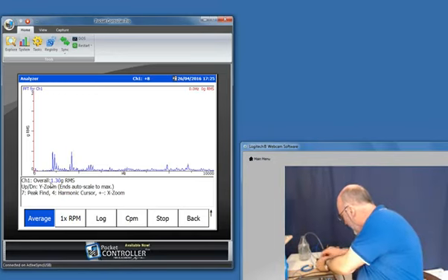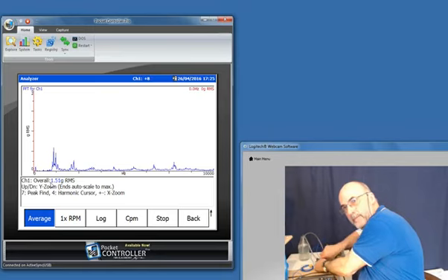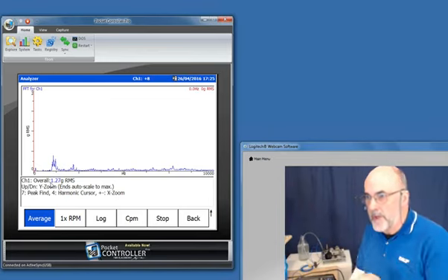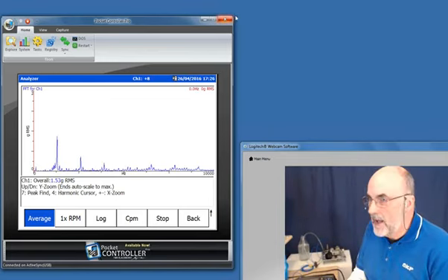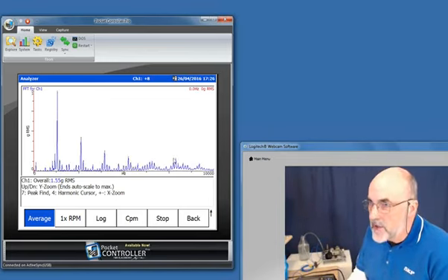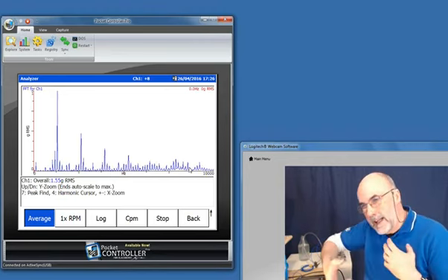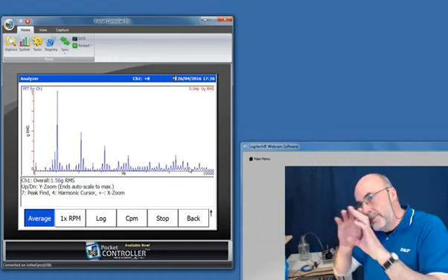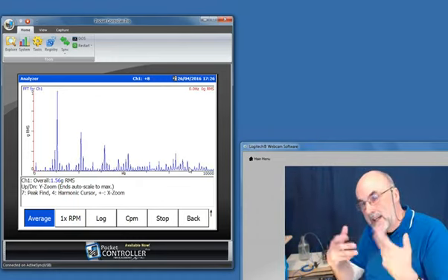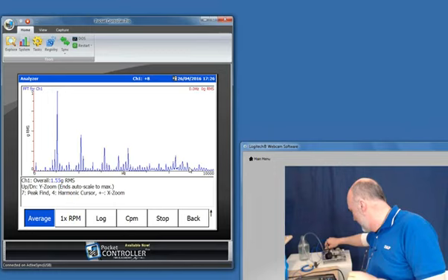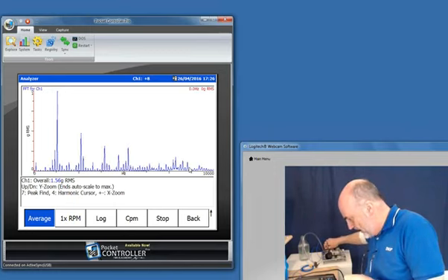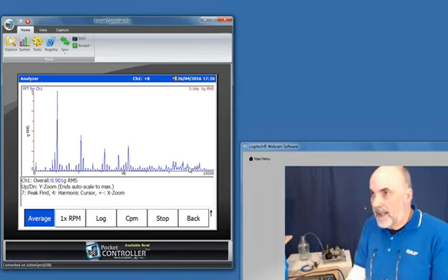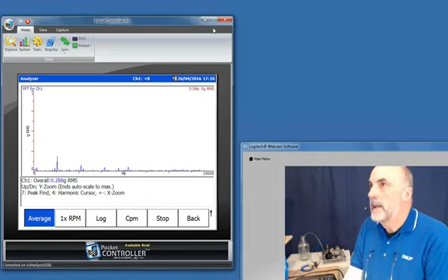Poor little pump is having a fit here, so I'll remove the cavitation. And you can see the picture updating. And as I said, that picture is the average of 10 readings, and you're taking another reading, throwing away the first. So it's smoother, it's more statistically correct, but it changes, it updates. Happy days. Get rid of the noise. So that's an exponential averager. Need to press on.